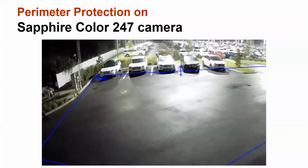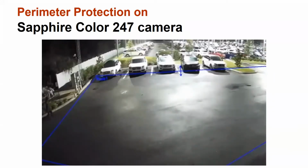Now here's another one, the whole perimeter protection. There's going to be a person walking in. As soon as he crosses the line, that triggers as a human crossing that area. And again, all those blue lines that you see there, you will have to draw them, and then select that it's for a human or a vehicle. So that's perimeter protection, and it's full color as well.